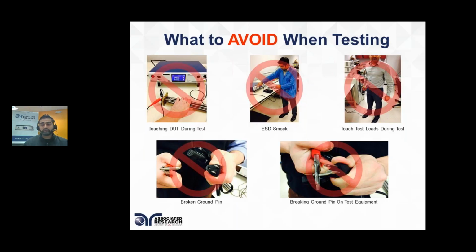You don't want to touch the test leads during test. That's a common notion, but we've seen requests about people playing around with test leads, not knowing what they could output. So you want to make your operators aware of what potential hazards are coming out of this tester. As recently as yesterday, we took a call about operators never reporting a shock hazard.